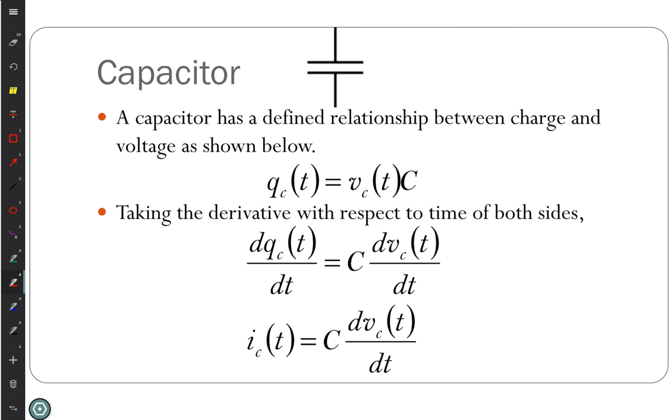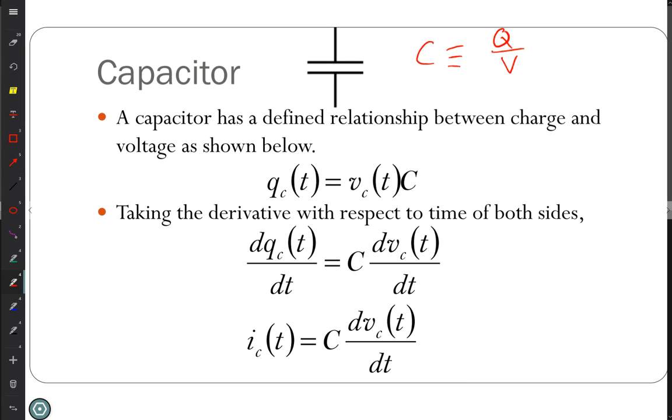For a capacitor, we define capacitance. Capacitance was defined by the equation: capacitance is the charge that you store divided by the voltage difference between the plates. When I said the charge you store, that was inaccurate. What word should I have said? Charge separation. The charge separation, because you're not storing charge. You don't have a capacitor with 10 nanocoulombs of charge on it. You have a capacitor with plus 10 nanocoulombs on one side, minus 10 nanocoulombs on the other side, if you're in a normal circuit.